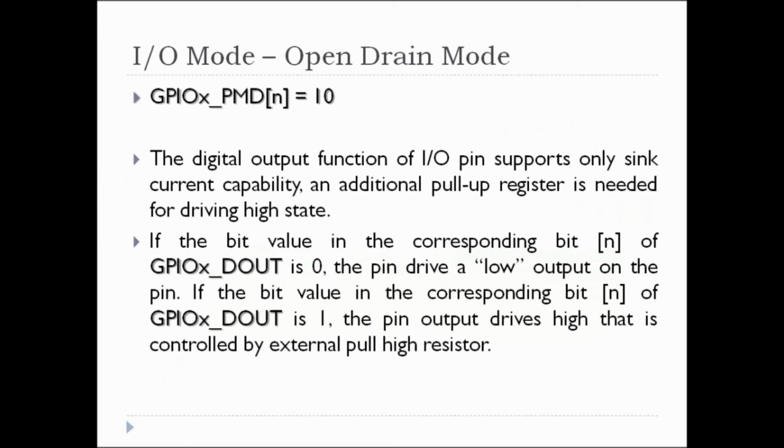If the bit value in the corresponding bits of the GPIOX_DOUT control register is 0, the corresponding pin drives a low output. If the bit value of the GPIOX_DOUT control register is 1, the pin output drives high, which is controlled by the external pull-up resistor.